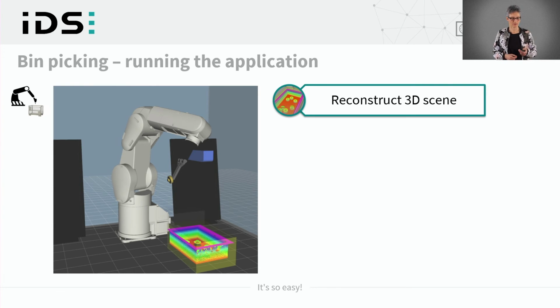First, you acquire the 3D scene and reconstruct it. Then you have all what is visible for the sensor in 3D data. And then you have to find out where is the object inside my scene. So best thing is you throw away most parts of the scene in 3D data that are not part of the objects. And then the next step would be the 3D matching to find out the object's position.